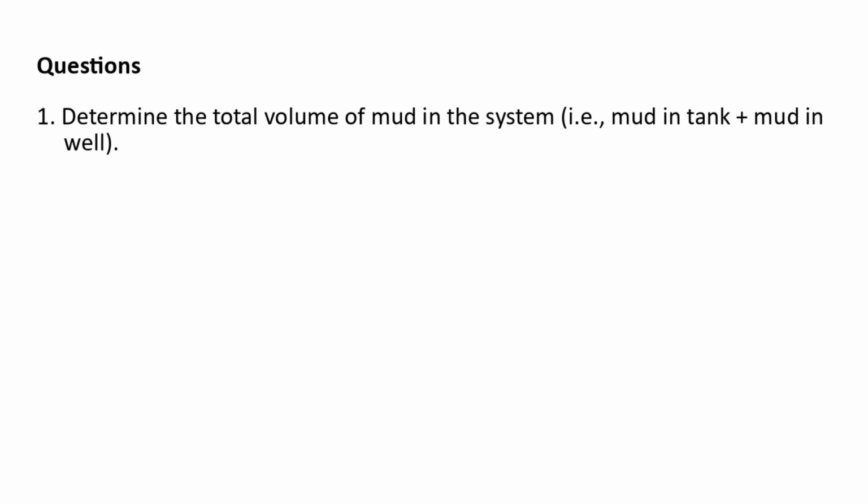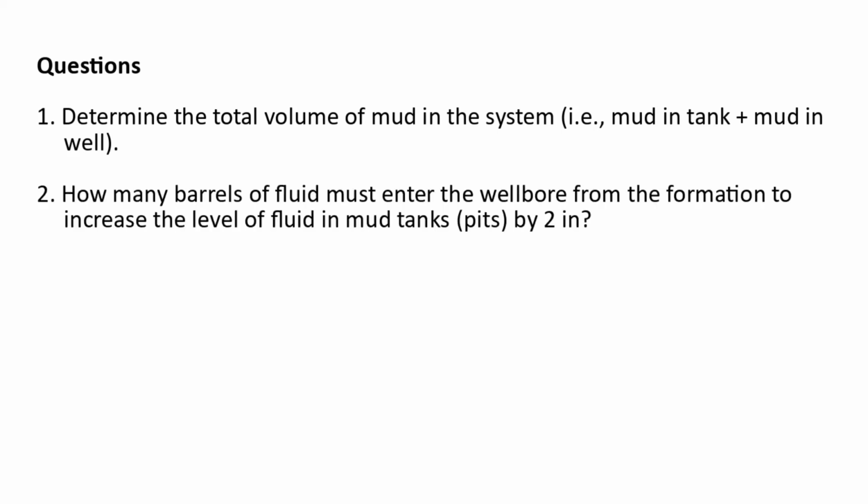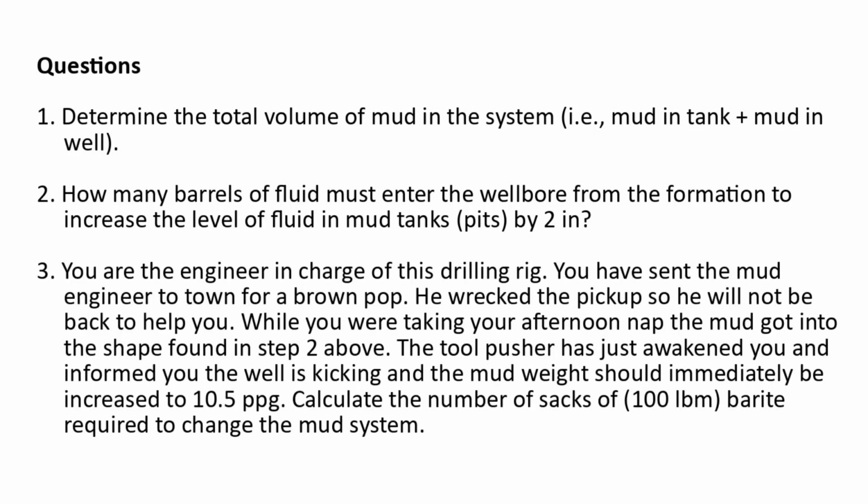To conclude the lab, there are some final questions you should answer. 1. Determine the total volume of mud in the system. In other words, the mud in the tank plus the mud in the well. 2. How many barrels of fluid must enter the well bore from the formation to increase the level of fluid in the mud tanks or pits by 2 inches? And 3. The long question seen on the screen now.